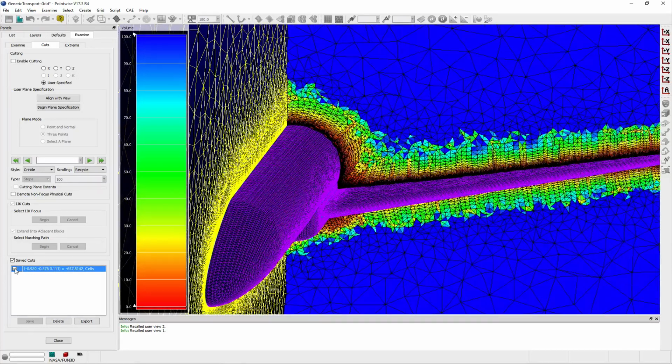However, if, for example, the tail configuration changed to a V-tail or Y-tail configuration, or a canard was added, then I may need to update the script to accommodate those changes. However, for shape changes to any of the included quilts, the script can help quickly automate meshing during experimental design or parametric trait studies.